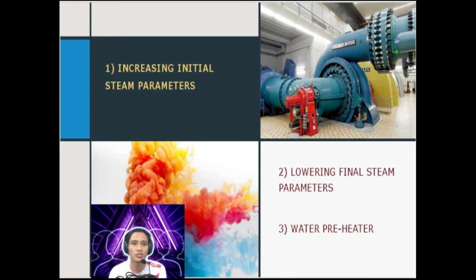As we know, most modern thermal plants use either a water-cooled condenser or an air-cooled condenser as the cold source in the cycle. Water-cooled condensers could be classified into cooling systems with open and closed systems. Air-cooled condensers could be classified into direct or indirect cooling systems.